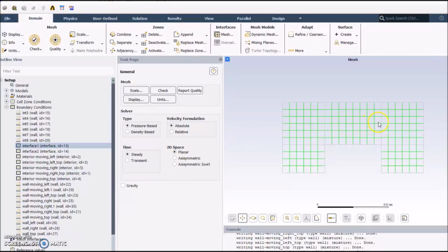So we exported the mesh to Fluent, and now I'm going to continue the next step on the Fluent side. So the first step is to create interior boundary conditions from these two interfaces that I created. Notice that when I click on that, it's going to show the related interfaces. One thing to notice is when I didn't use the word interface for these interfaces, it assumed that these name selections are one, which we are going to change later on, but that's an interesting observation.